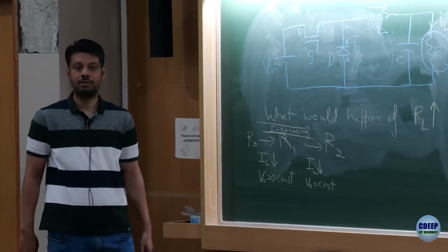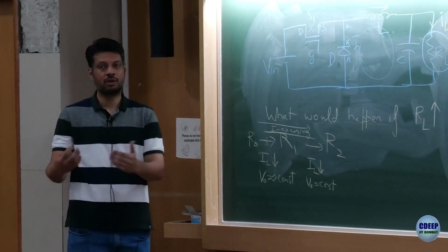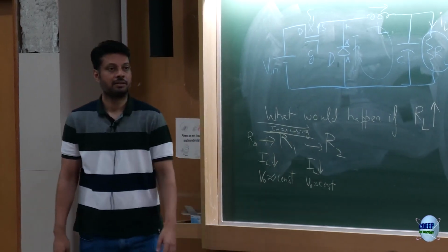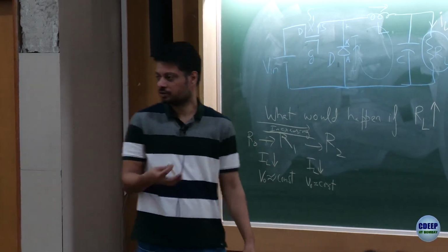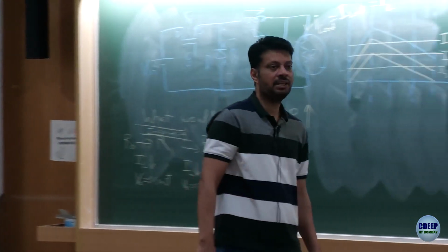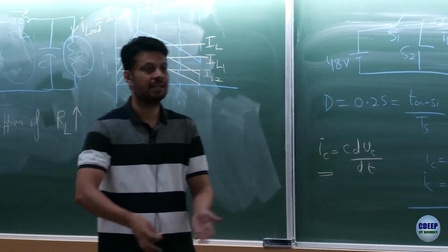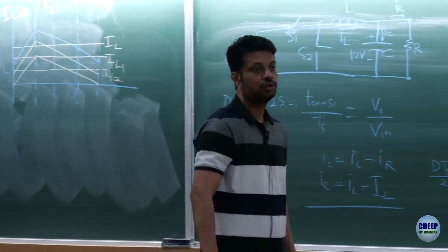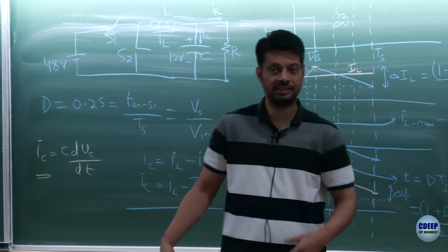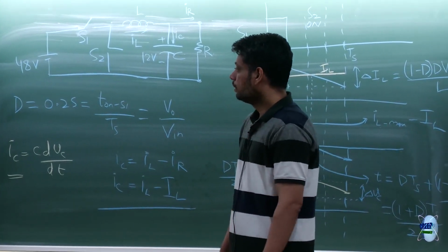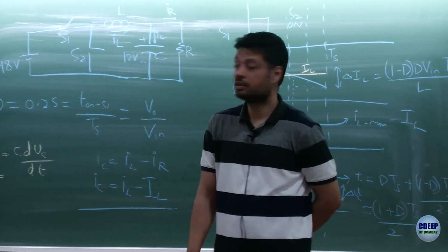When we say we reduce the load power or the load current, that means we are increasing the resistance. We have been following this in transformers also. When we say we reduce the load, the kVA of the transformer load comes down and therefore the current comes down, so the impedance or the resistance actually goes up. So far so good. Any doubt till R2?